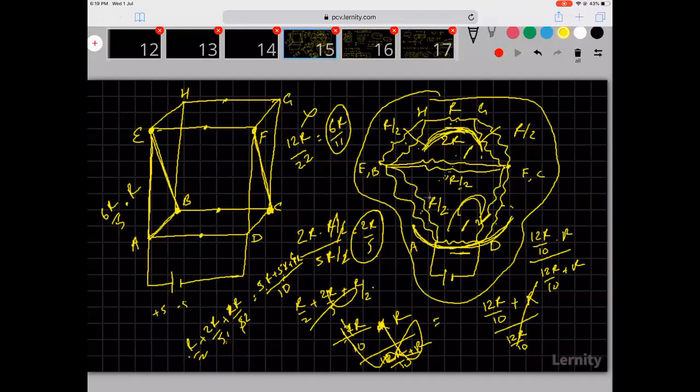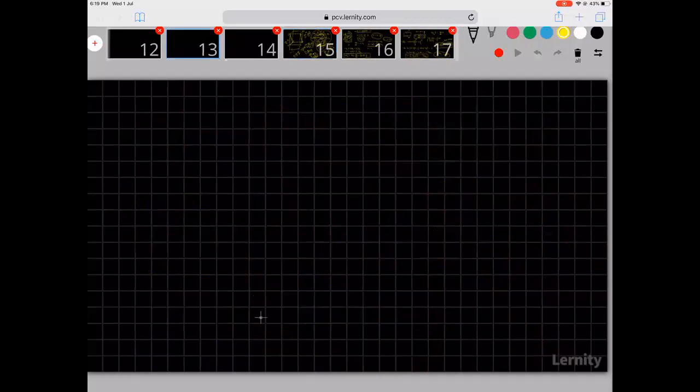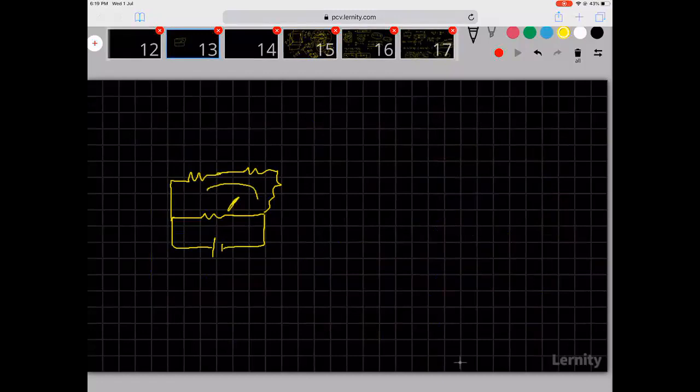I'll just explain to you here. See, you have one resistor here across which you have the battery. Then you have this, then you have this, then you have this. So what can you say? These are in series. Then what can you say about this? They are in parallel. Always you should work from the furthest end. Never work from the nearer end. So keep simplifying only the furthest end. Nearest end you can't work. So the moment you understand this technique, you will not make mistakes.